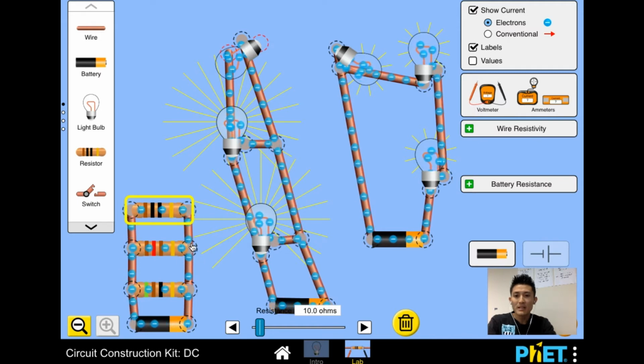And so notice that because there are different amounts of resistance, and they're all in parallel, the current, however, is going to be different. The rate at which these electrons are moving through the circuit is going to be a little bit different depending upon the resistance of these resistors. However, parallel circuits do seem the most effective when we're stringing lights together, or when we have certain appliances strung together, or your outlets in your house, for example, should be in parallel rather than series, just in case one of them goes out, as well as the even distribution of the voltage.